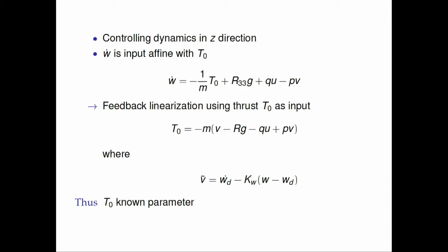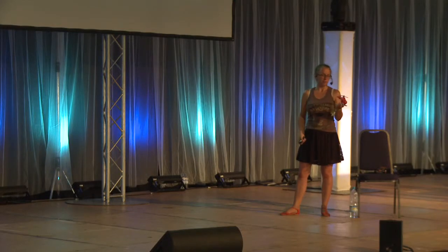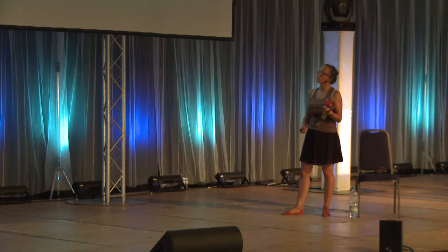And when we choose the appropriate equation, we just see, okay, the translational velocity has just the thrust of the main rotor because, well, it's just moving up and down. Then we can stabilize it pretty simply by using feedback linearization, so we're just feeding back where we are.